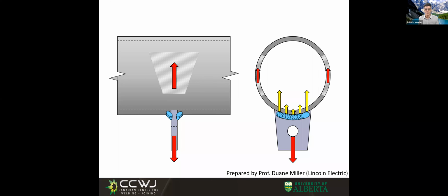And here, we would have a very uneven distribution of load on the weld. Very similar story as before. The more vertical we are, the stiffer we are. The stiffer we are, the more load we take. And this part, as it starts to become more vertical, it starts to take more load. This part in the center is very compliant, takes little load.